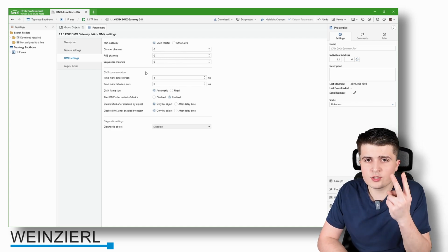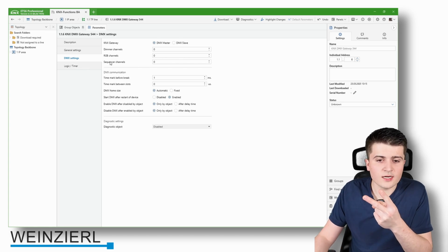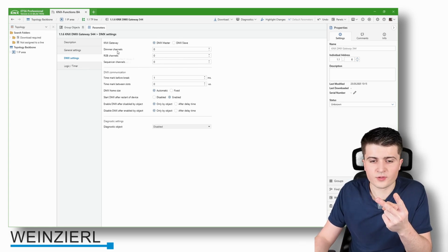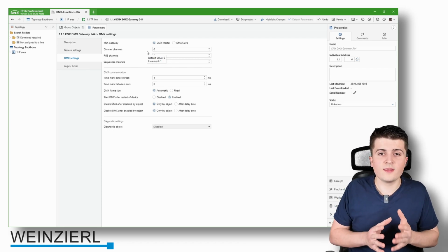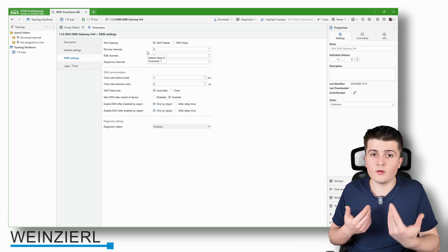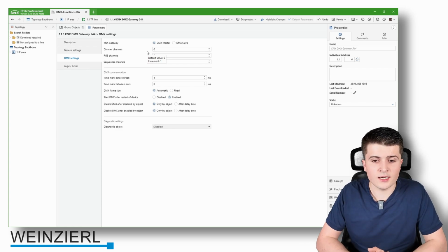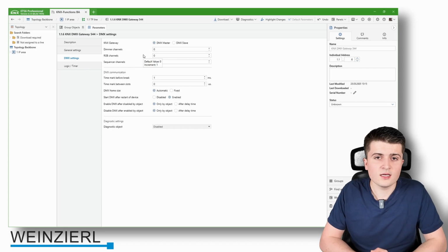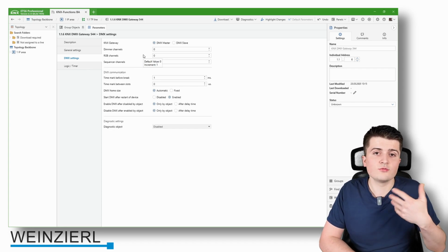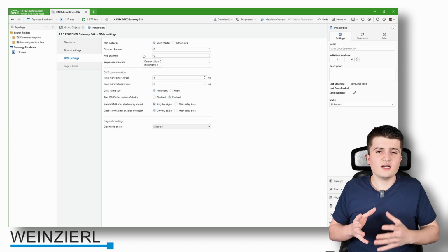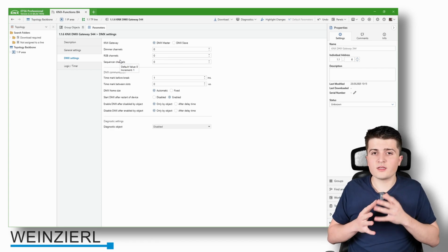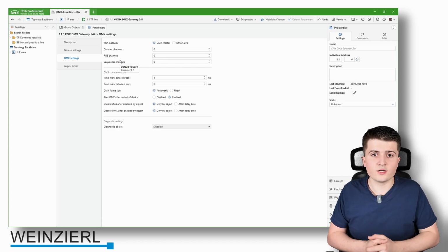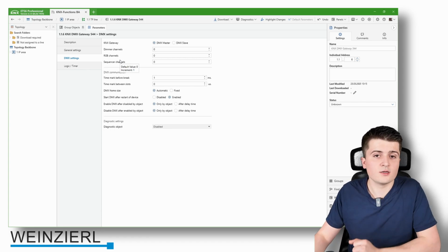And basically there are two different kinds of channels beside the sequencer, which I will come to shortly. So first of all, we have the dimmer channel. That is basically just a 0 to 100% value that can be sent onto the DMX bus to one or multiple addresses at the same time. And then we have RGB channels that are basically 3 addresses combined to one RGB object. Because we saw DMX itself only knows those 0 to 100% values, and with this RGB channel, the gateway itself is decoding the RGB value into the 3 different percentages for red, green and blue.